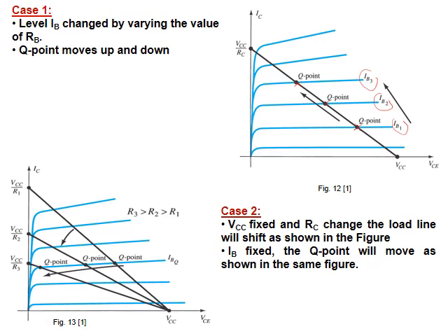And this reflects that, rather than having VCEQ here, it becomes here, or if we increase IB more, it will become here. So this means that increasing the current IB will reduce the VCEQ of the transistor. Take this picture and put it aside.